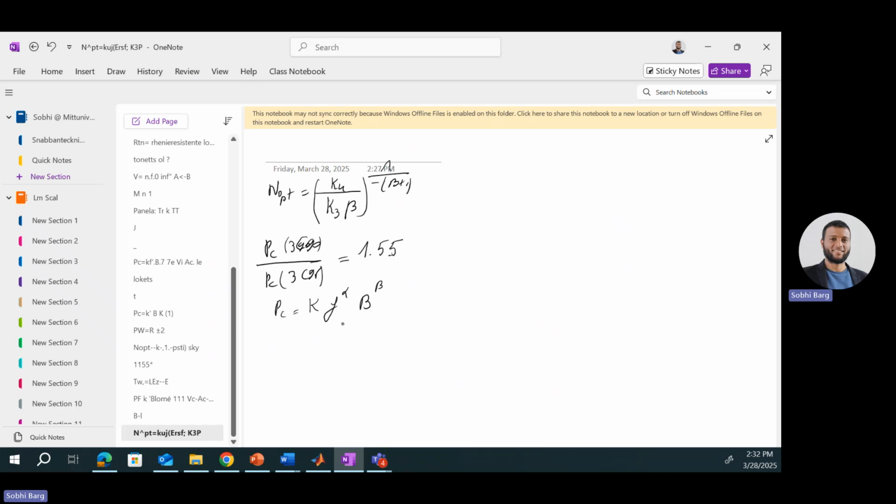But let's understand this equation, because these parameters, beta, alpha, and k, depend on the magnetic material. So it will be a problem if we divide this for two different materials. But for a given frequency and a given B and a given temperature, this equation could be written as follows for both materials.